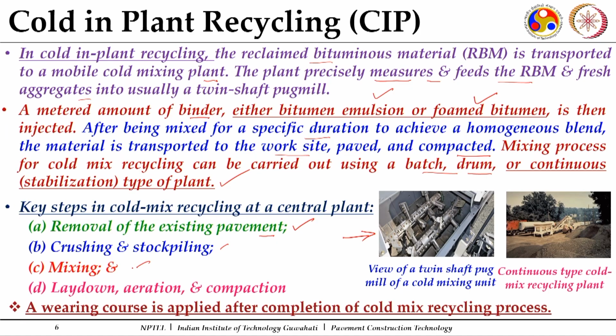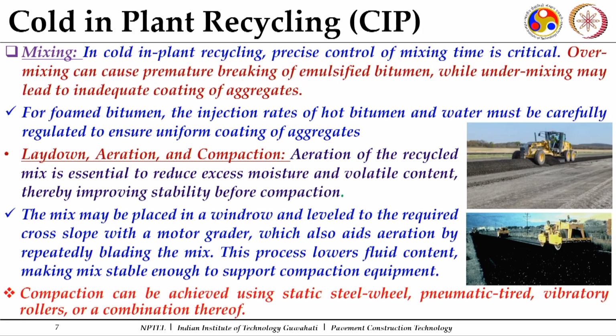Then the mixing is there using different recycling agents, emulsified bitumen or foamed bitumen. Then lay down; since it is an emulsion, there may be a requirement for aeration. Thereafter the compaction and curing requirements will be there. So, these are some specific requirements. We will discuss these requirements in upcoming slides also. And finally, since it is laid as a base course, on top of it you need to go for a bituminous wearing course.